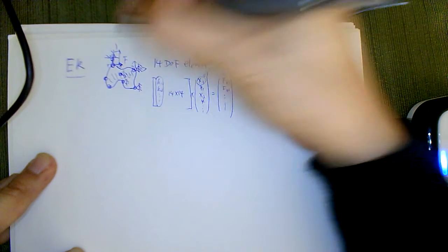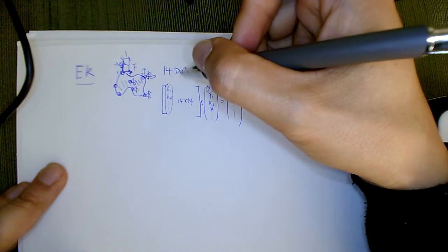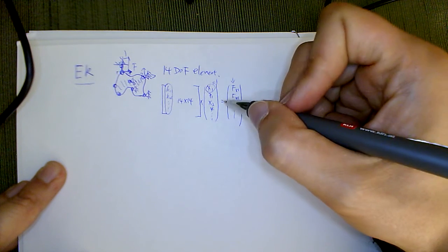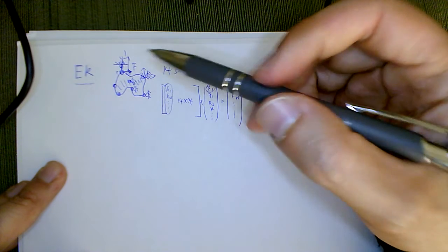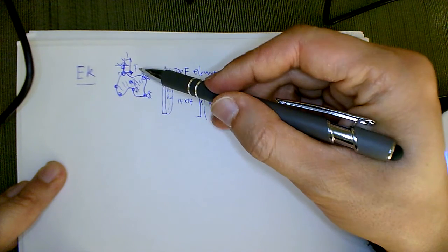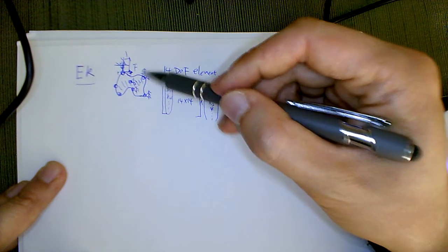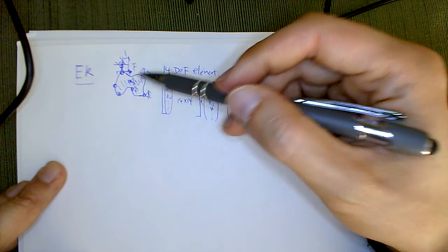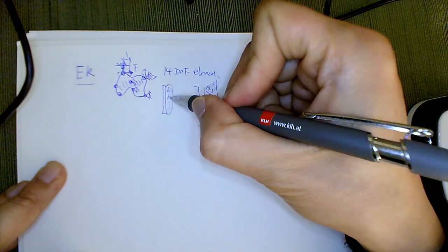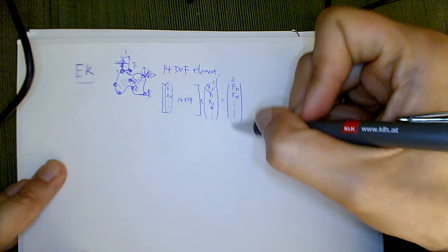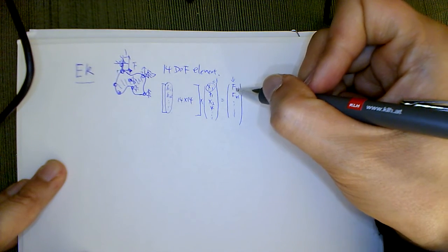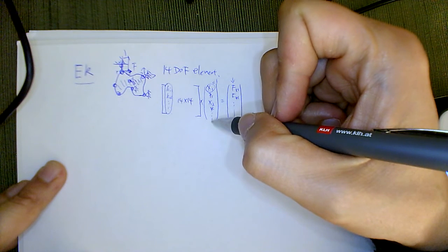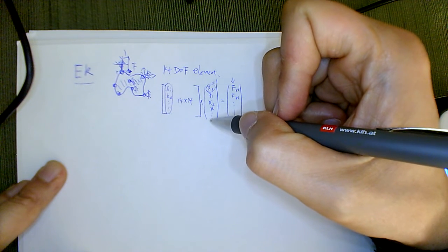I'm going to force this element to move as 1, 0, 0, 0, 0, 0 all the way along. If you can find out how much this force is, and what the reaction forces are at each of those to hold them at 0, you essentially have those forces by definition, and you have the first column of your stiffness matrix.